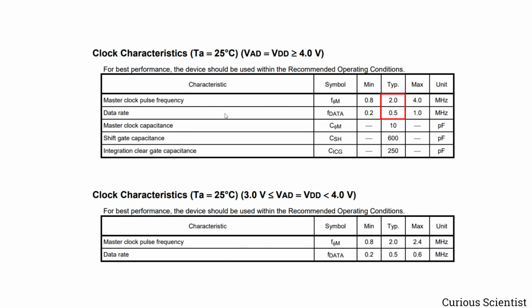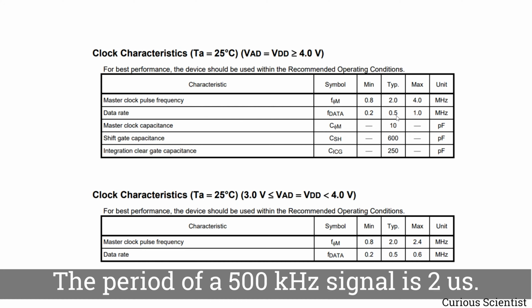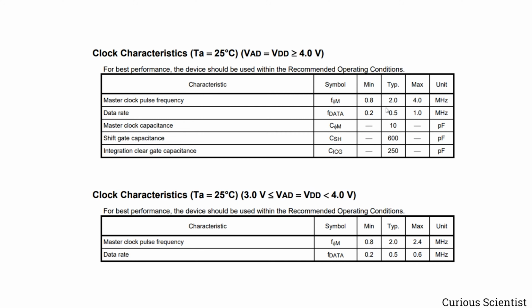So this is the rate how the useful pixel values are shifted out, and here that is 0.5 megahertz or 500 kilohertz. So again, we know the next thing that we have to know about is that the data rate of our AD converter has to be 500 kilohertz, which means that the signal of the timer which triggers the AD converter has to be triggered with 500 kilohertz.